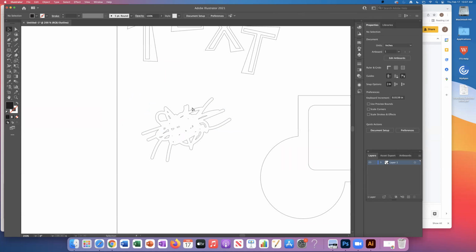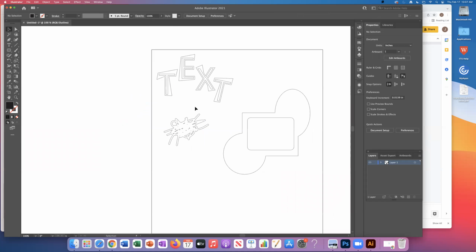So when we're working with Illustrator, we're going to be building text and forms and objects and drawing. But ultimately, this path view is going to be the best way that we can understand how the laser is going to recognize this work, and imagining what will cut out and what will remain intact, right? And so you're wanting to look for areas where there's crossover or paths that intertwine into one another.